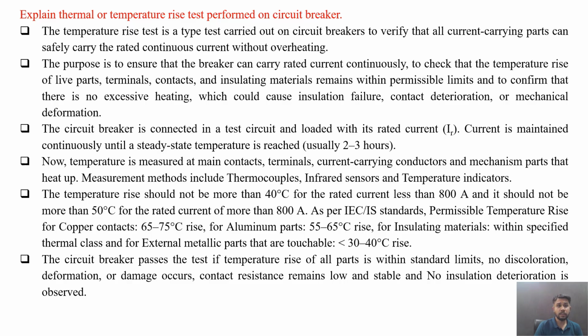Explain thermal or temperature rise test performed on a circuit breaker. So the temperature rise test is a type test carried out on circuit breakers to verify that all the current carrying parts, that is contacts, can safely carry the rated continuous current without overheating.